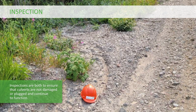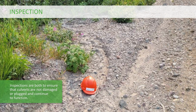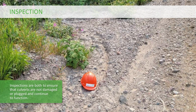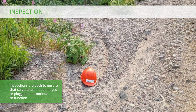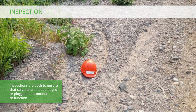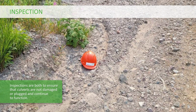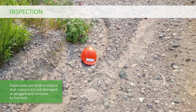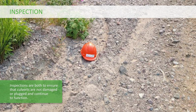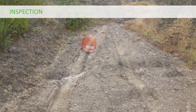Inspection. Inspection of water management structures should be frequent to ensure the resource road continues to perform as intended. The force of flowing water and lack of water management can have severe consequences with respect to erosion and sedimentation. Planned and ad hoc inspections are both needed to ensure that culverts are not damaged or plugged and continue to function, with offtakes free-flowing and not ponding water.